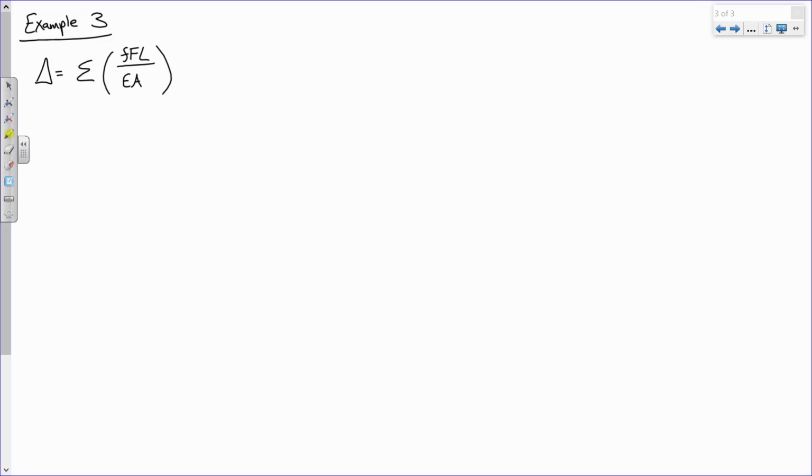And another thing to keep in mind when it comes to solving the deflection on trusses, remember there really is no other way of doing it other than an approach like this. All right. Now we have an E value of 29,000 ksi. We have an A value of 2 square inches. So right off the bat, we can go ahead and make our life easier and say that EA is 58,000, and that the units come out, that's kips. All right?